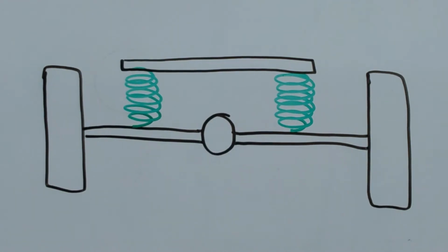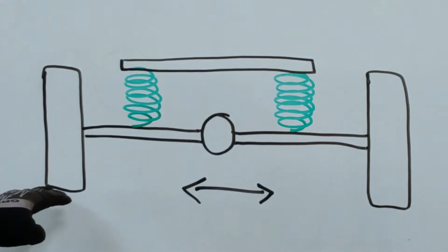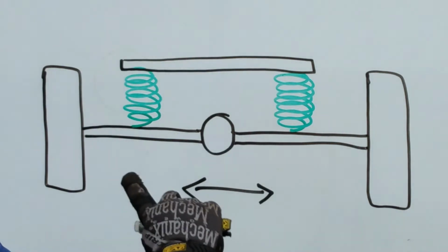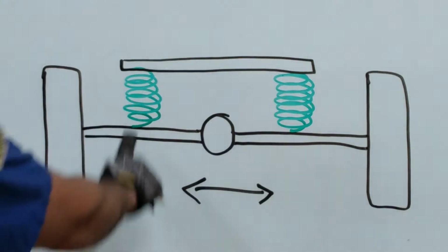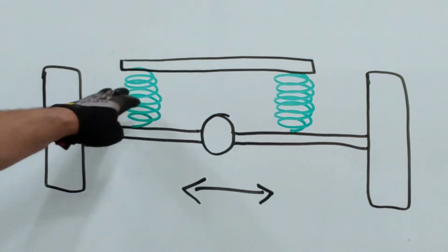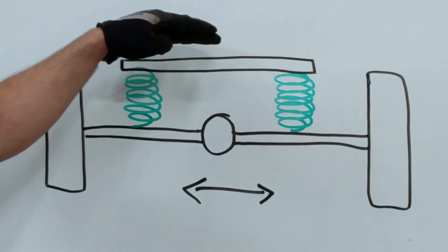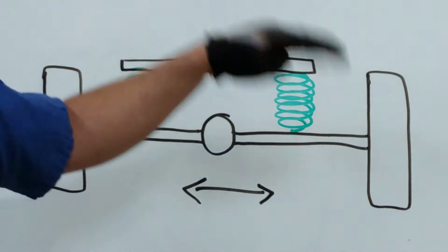The vehicle is going to be subjected to lateral forces, whether that's due to gravity and traversing a side hill or an off-camber road situation. As the vehicle is handling across lateral forces, the axle is connected to the ground through the traction of the tires. Those forces going one way or the other, that energy is going to transfer through the springs themselves. Now, without any control links, the chassis is not going to be stable on the coil springs.